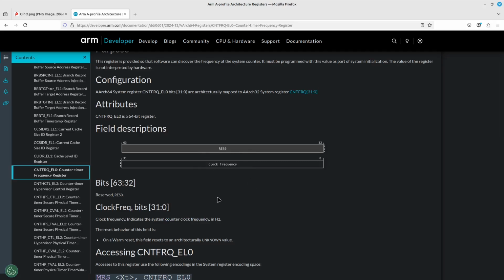Now, back in the olden days, way back when, instead of using hertz, they used CPS, or cycles per second. Clever people naming things what they are. However, now we use hertz. We will be timing in milliseconds, so we will want to know cycles per millisecond. And I don't know if millihertz is a real term or not. Maybe it is. Anyway though, whatever number this is, we will want to divide it by 1,000 because we want to convert it from cycles per second to cycles per millisecond, which is 1,000th of a second.